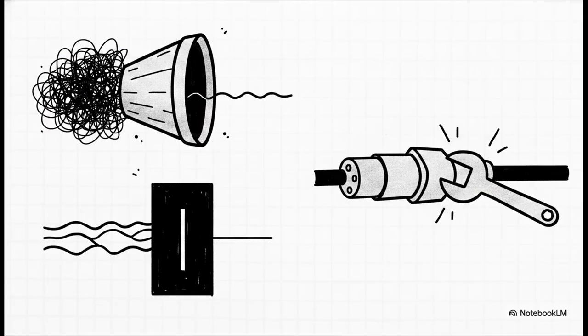The most counterintuitive but wildly effective fix for blocking is turning on an attenuator. Yes, dropping the signal. The secret to hearing a weak signal better is sometimes to make your radio deafer on purpose. This brings the receiver out of gain compression and back into its linear region, magically making the weak signal copyable again by preventing the front end from choking.